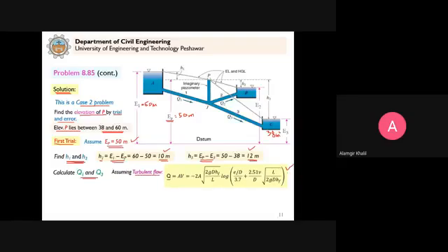So you can directly calculate Q1 and Q3. There is no friction factor in this formula, but the assumption is that we have turbulent flow. After we calculate the values, you have to calculate the Reynolds number, and it should show that the flows are turbulent. Only then will these results be correct. So this is the assumption that we have to make.